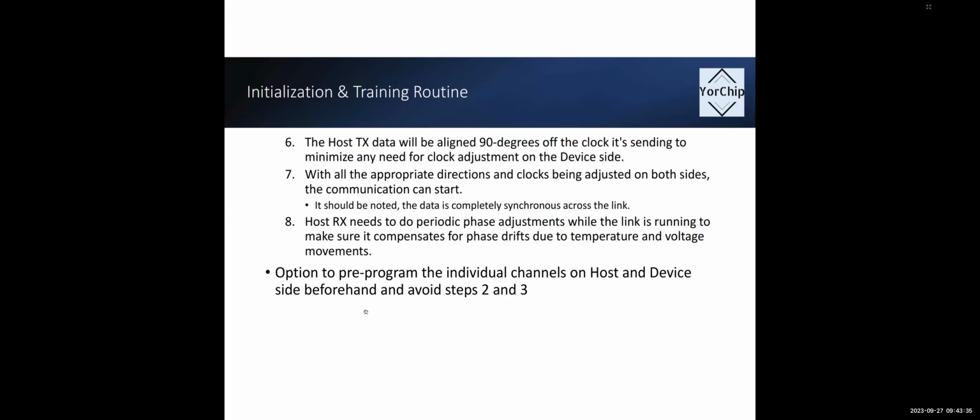You have the receive latency: you receive the clock and then you have to distribute it across your channels. Those are somewhat process dependent within the device side, and you have some control over it. So as long as you can compensate for that, you can do something. But again, it's a very simplistic view. The moment speeds start to go up, that starts to be a problem.